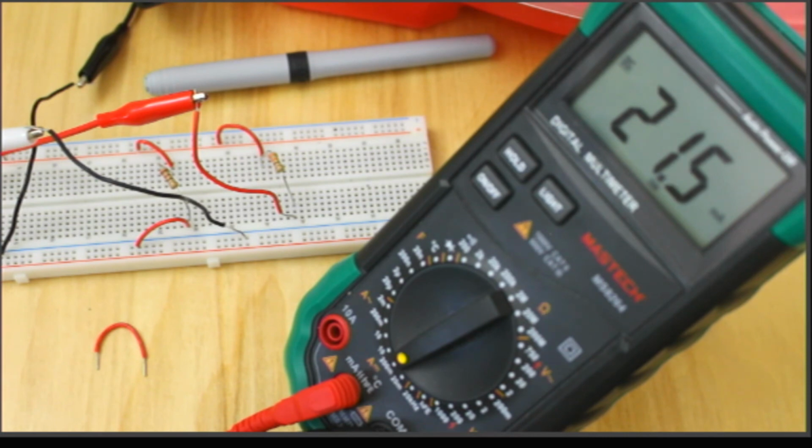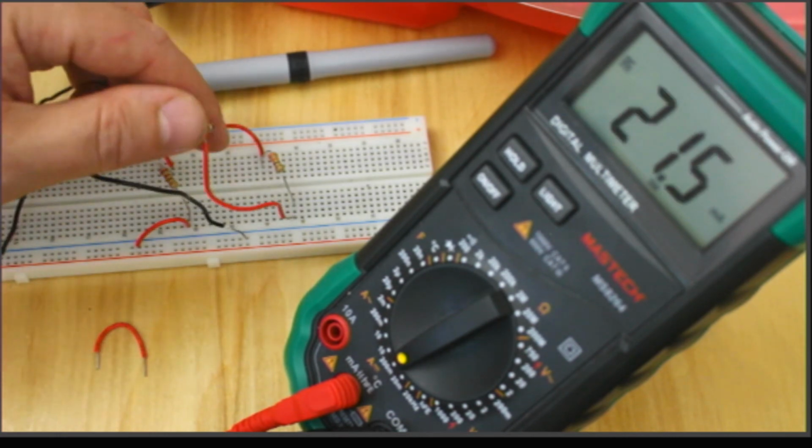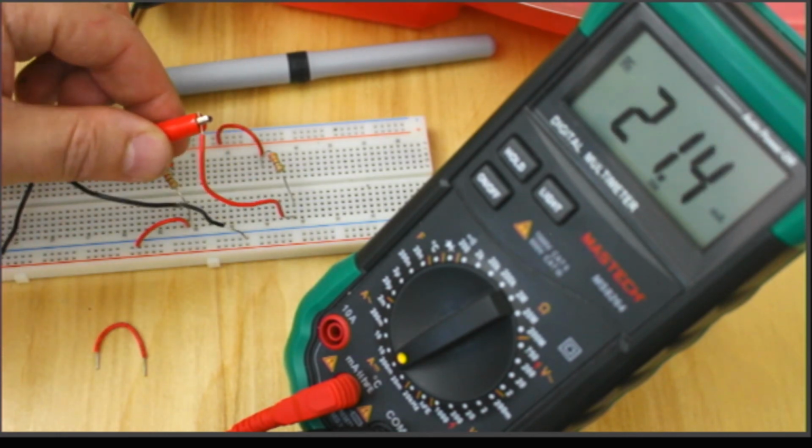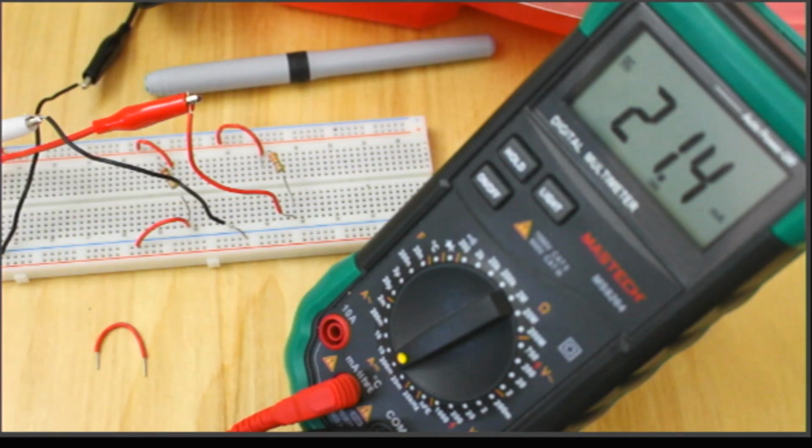So we're about 3 or 4 milliamps off in each case. And so if you did the ratio of the two, they would still have the same ratio as 37.3 and 24.8. Okay? But anyway, I think that's the easiest. If you don't have a lab partner to help you, then putting these alligator clips on your leads out of your DMM, and then having a little wire that you can put in the board, just makes it a little bit easier, because right now I'm not touching anything and it's making the measurement.